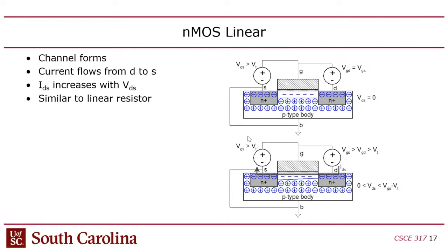You can change the voltage. Generally, if you want to increase your clock rate, you need to increase the supply voltage and the clock rate together. But you can't really go much below 0.8 or so, because you start to get close to the threshold voltage.